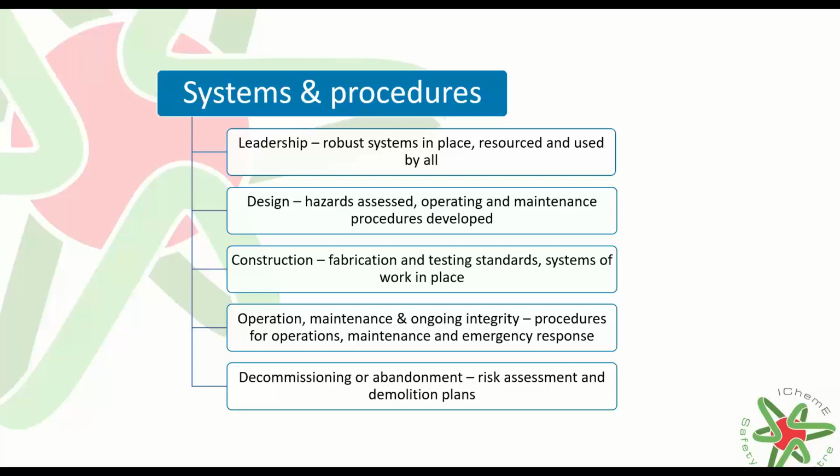Because I used to work in an industry where, because it revolved around safety of aviation, we used to have a saying, if it's not written down, it never happened. So you'd need to do checks on the fuel quality, for example, every day, and you needed to write down the density of the fuel, the colour of the fuel, the temperature of the fuel. And if you didn't write it down, well, you didn't check it because there's no evidence that you ever checked it. So if it's not written down, it never happened.